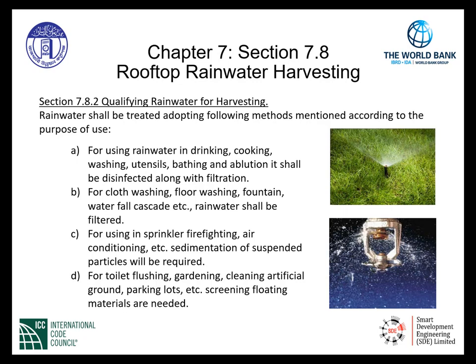As you can see, B differs from A in that we will not be drinking the water as indicated in item B. Therefore, disinfection is not required. Only filtration is required. Item C, for using in sprinkler, firefighting, air conditioning, etc., sedimentation of suspended particles will be required to be filtered. Item D, for toilet flushing, gardening, cleaning artificial ground, parking lots, etc., screening floating materials is needed.